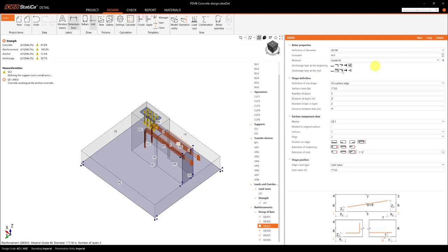Okay, so the first option means there is no connection between the end of the rebar and the concrete. Then the 90 degrees and 180 degrees hooks are representing 0.3 times the spring. So it's anchored to the concrete 30%, let's say.